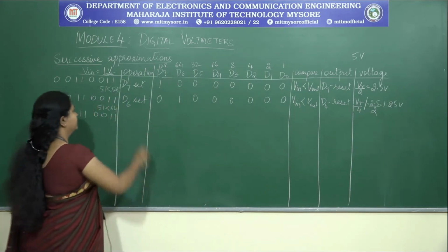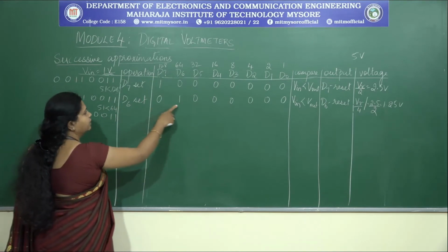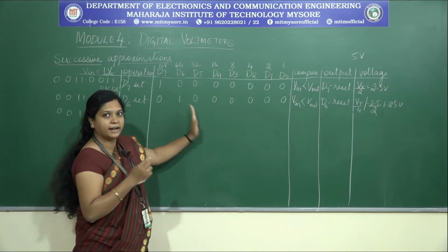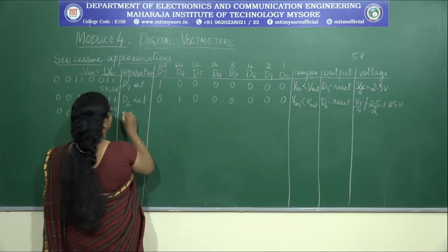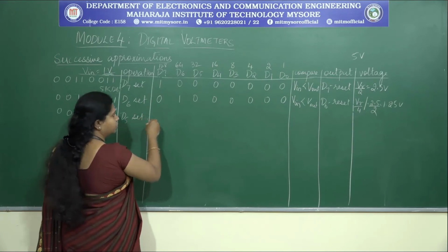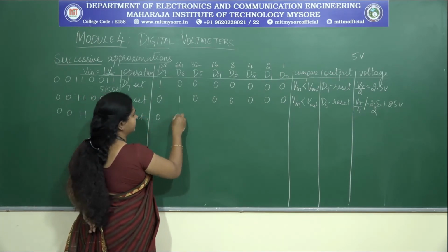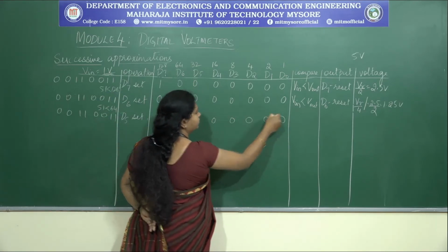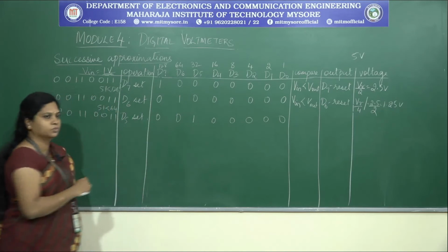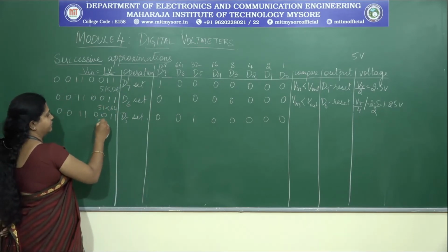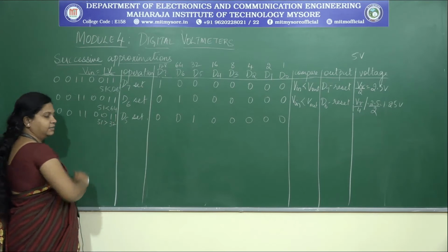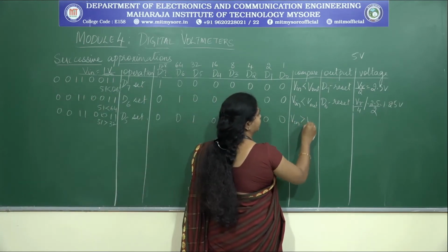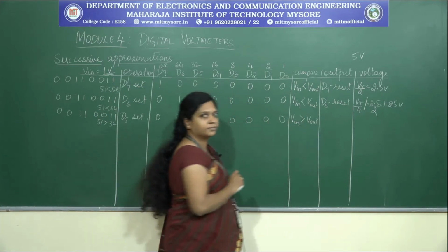Next you have reset the bit. Now the next cycle, since Vin is less than Vout, you are going to clear this and add a new weight. So again D5 should be set now, a new weight should be set. Reset this, set bit 5, 0, 0, 0, 0, 0. What is the value? 32. What is the value we have taken here? 51 is greater than 32. Now the condition is Vin is greater than Vout.